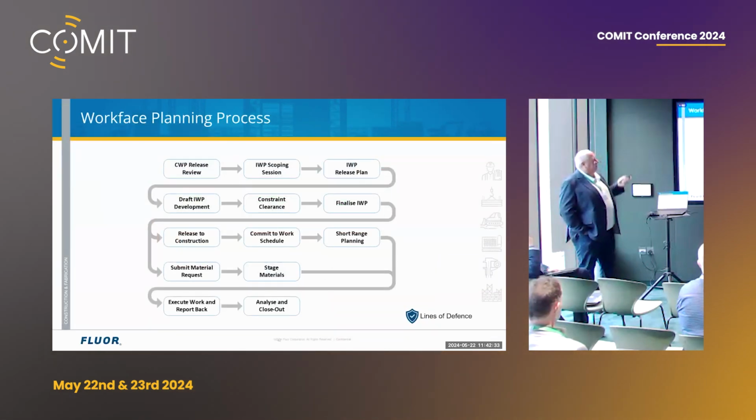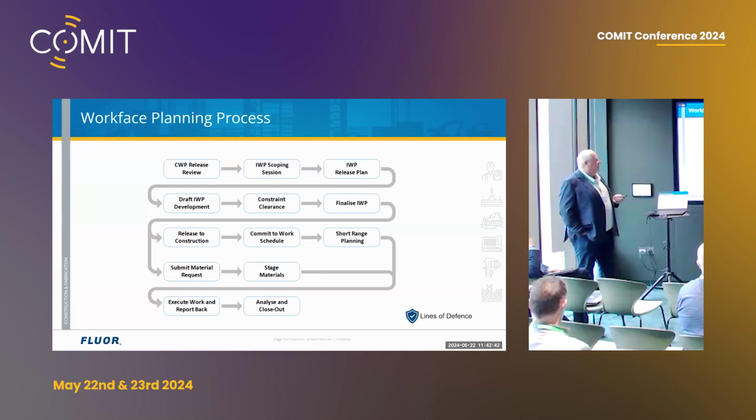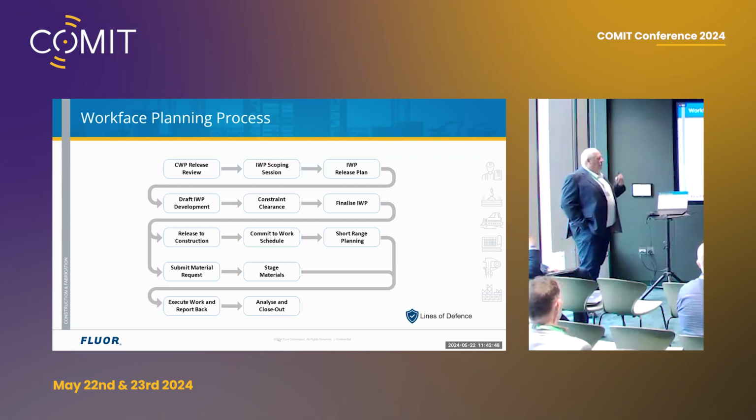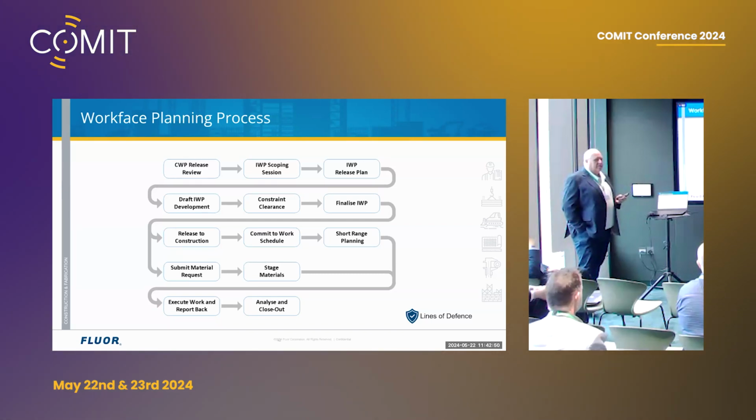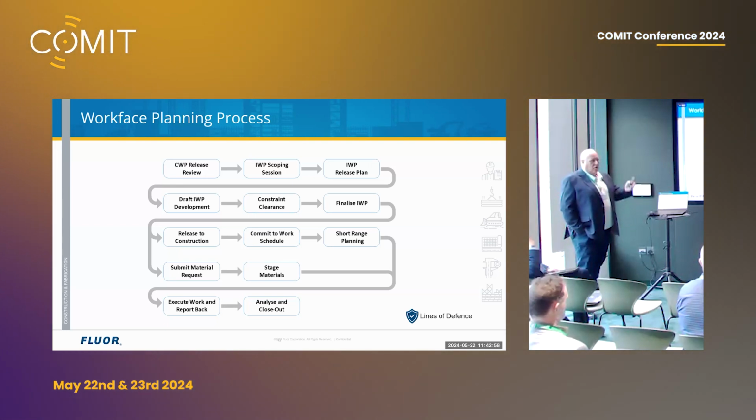So our workplace planning, as I said, CWP release, nice handover, finds so many engineering issues that engineers don't want to listen about, don't want to know about. So we find that so we can resolve them before it goes to the field. We also find if there are any design changes coming on, because they're the bits that kill us in the field. Get a design change when you're installing, you either stop work, leave it unsafe, or you finish it and then come back to a rip and tear.